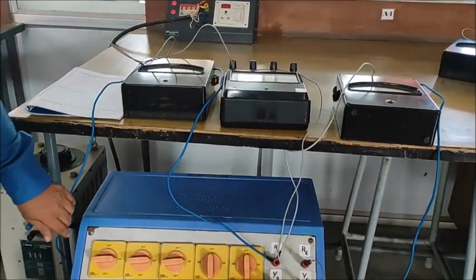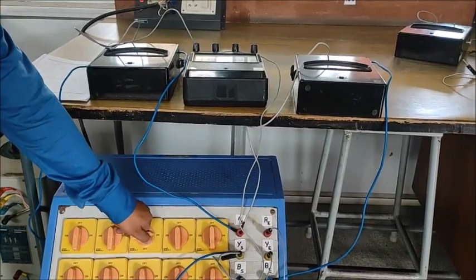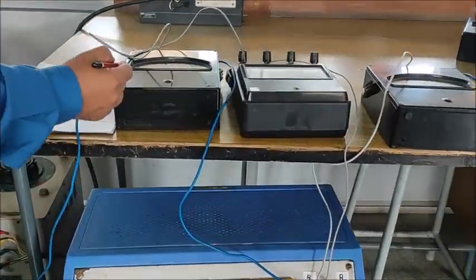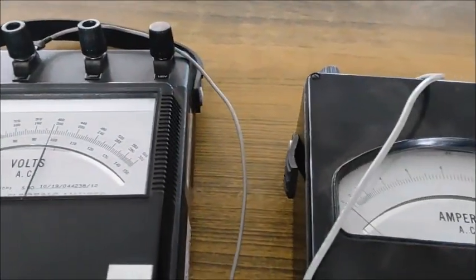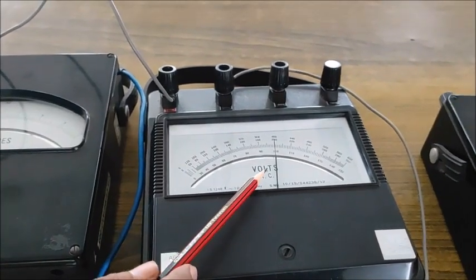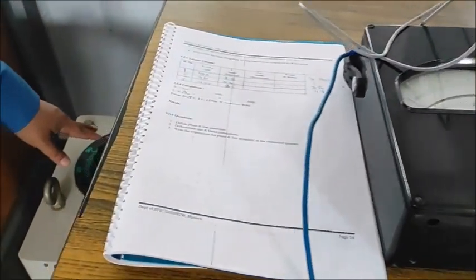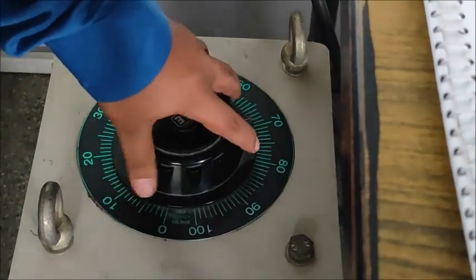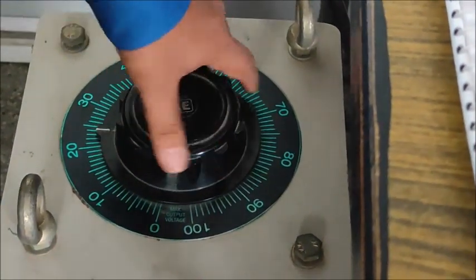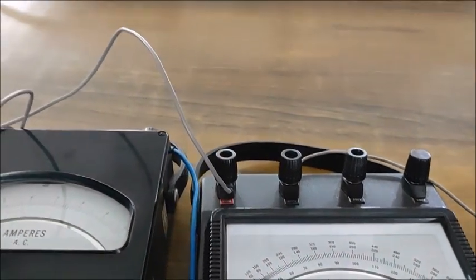Okay, so the procedure to turn off the circuit is, first of all, you have to turn off the loads, and you have to ensure that the ammeter is giving you 0 reading. Then you have to bring this voltmeter back to the 0 position. That you can do by rotating this switch back to the 0 position. Whenever you rotate this, you can observe that the voltmeter comes to the 0 position. Okay, so this is the procedure to turn off.